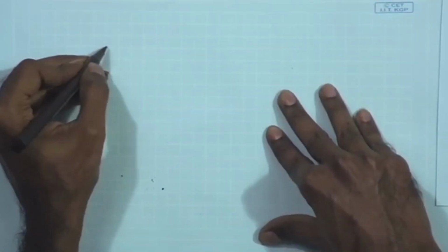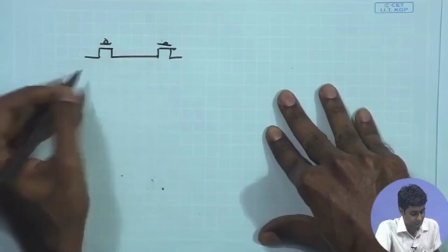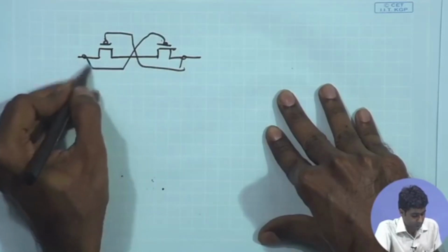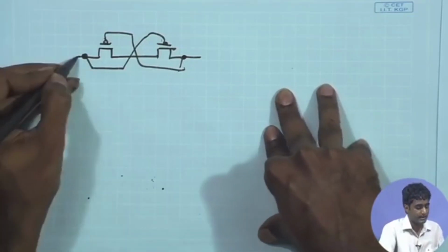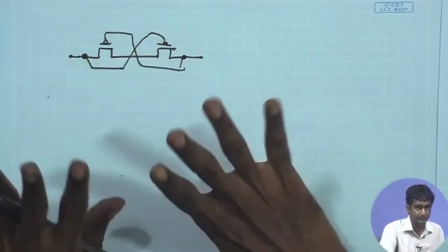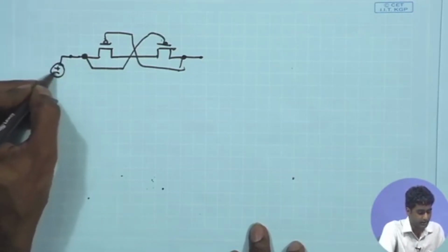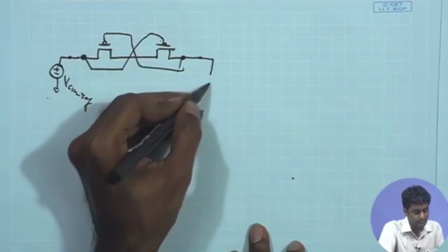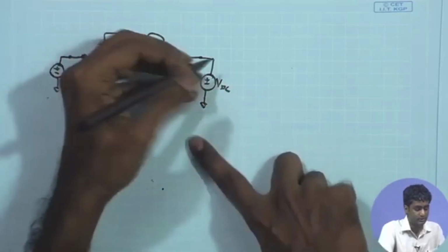If you look at the RF, the way we created it using the transistors that you have, remember the connections are only at the dot. Wherever you have the dot, this is no connection. And here also, in order to characterize this and try to find out the impedance of this, one easy way to do it is apply a DC potential over here, which is VCM ref, and then apply some VDC over here, and in the DC sweep analysis, basically you can try to